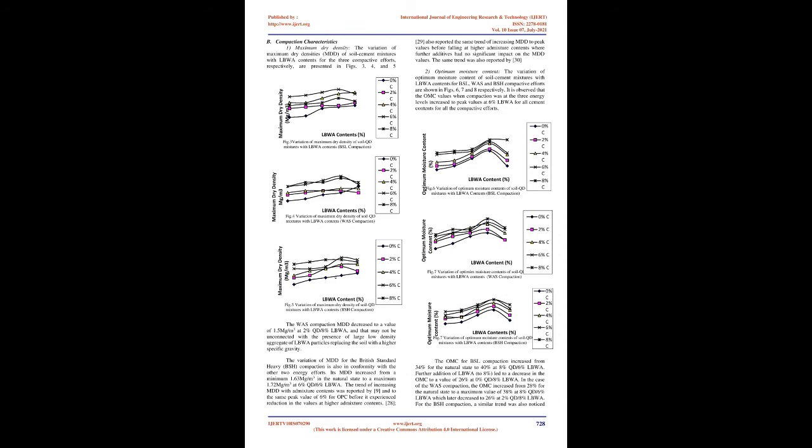The soil has a free swell of about 55%, soak CBR values of 5%, 6%, and 9% for the 3 energy levels of British Standard Light, West African Standard and the British Standard Heavy, respectively, and UCS values of 251, 364 and 687 kN/m2 for the energy levels, respectively. The soil was found to be highly plastic and falls below the standard recommendation for most geotechnical construction works, especially for sub-base or base courses in highway construction 26, 27.